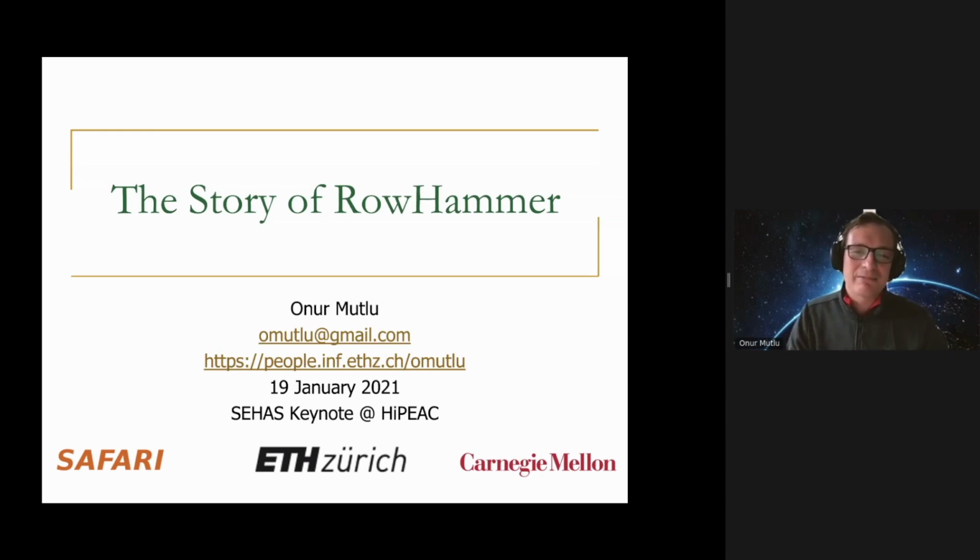So I think what you mentioned may be applicable to the access transistor, but there are bigger problems with the capacitor also in DRAM. Now, I'm not the right person to look into exactly device level solutions, but what I've read and investigated points to the fact that whatever technology you implement internally is going to have difficulties with read disturb because you don't have enough isolation when you go into a density that's too large, basically. I hope that answers it. We can have more detailed discussion.